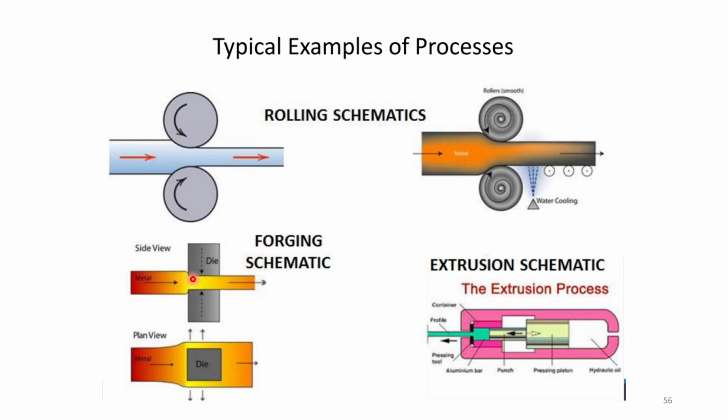In case of forging, there is hammering that is done after putting material through the die. In case of extrusion, your material will be in semi-solid form and this will be squeezed through one of the openings, and this will provide you products with uniform cross section. So very complex shapes can't be made using extrusion.